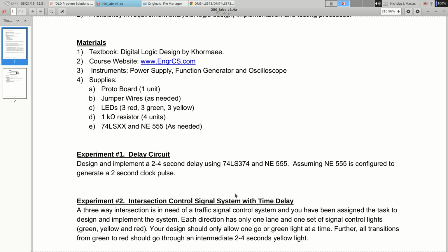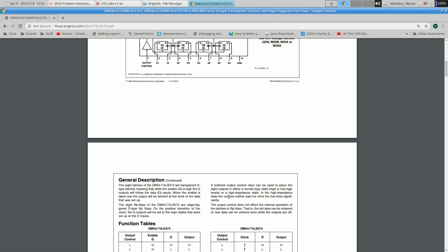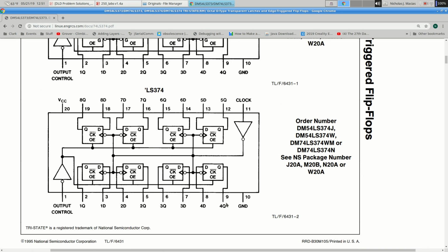You've got a 555, you've got all the setups, you've got the component ID block showing where power and ground are. Take pin 3, run it into pin 11 on this. And then, I don't know, maybe take your input, put it on pin 3, take pin 2, connect it to pin 4, take pin 5, run that to your output. Show pin 1 connected to ground, and then mention your ground and power connections in your component block.